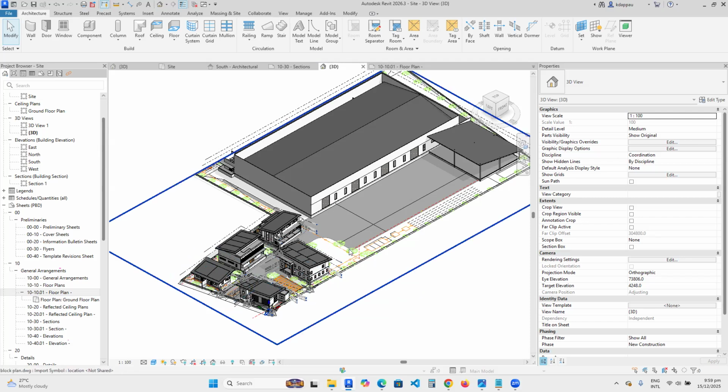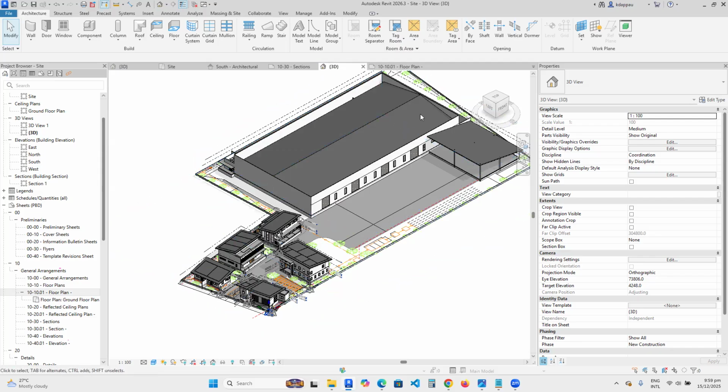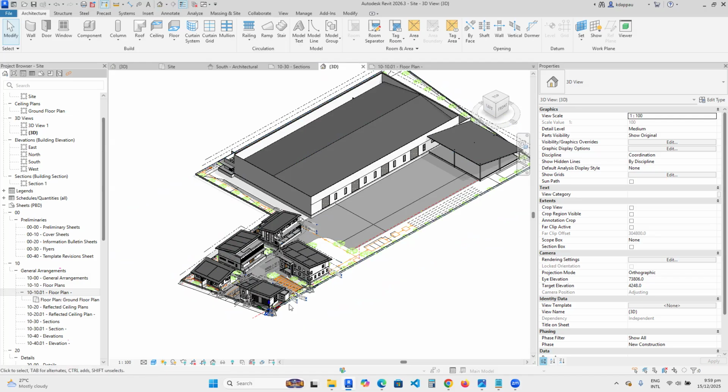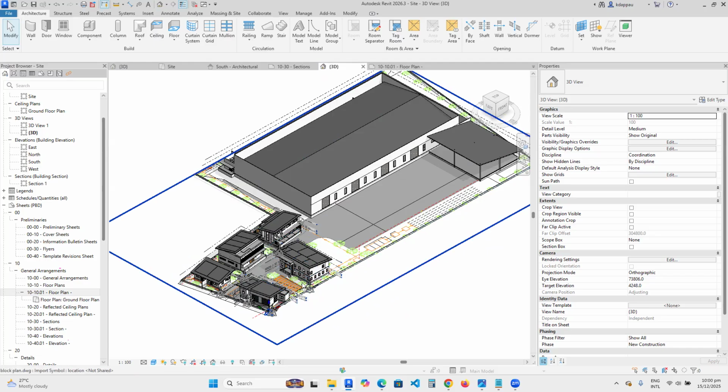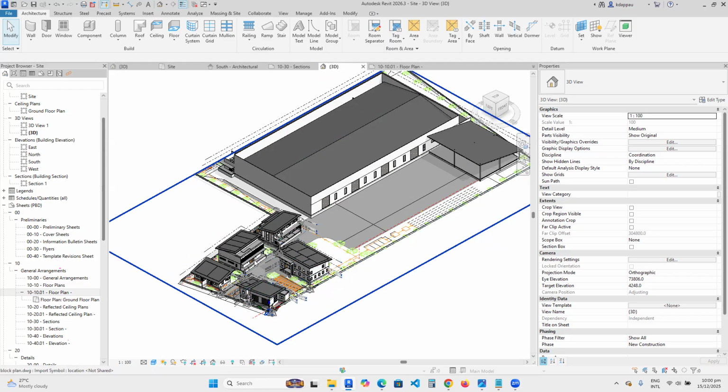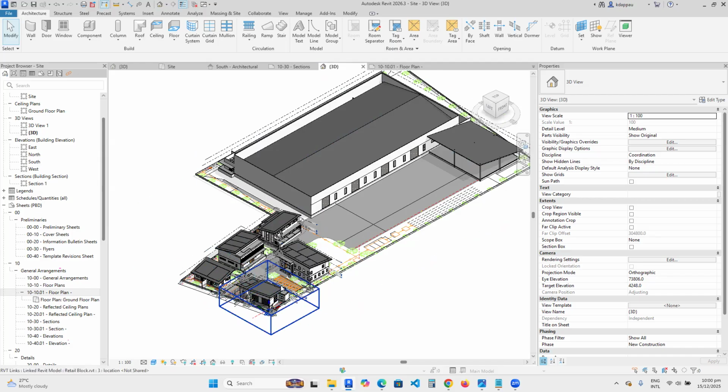But when you come to the site and you are modeling the site, like I said earlier when we started the class, you model the site and then show the topographical levels of the site, the contours and everything. Everything will be seen on the site. Then where you are going to place each building, we are going to define what you call a building part. And that building part will define the elevation at that location. So when you create a building part, some building parts will have low elevation, others will have higher elevations. So after defining those parts, you just bring in the building and then position them at the location where the parts will be.